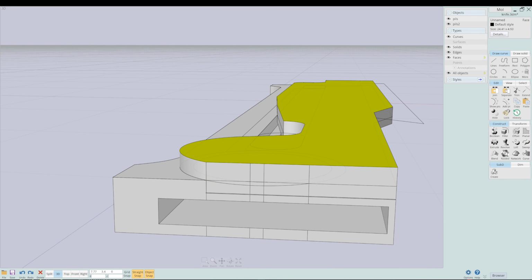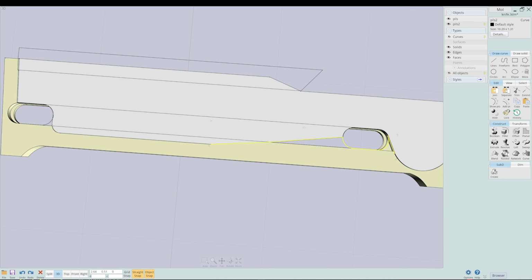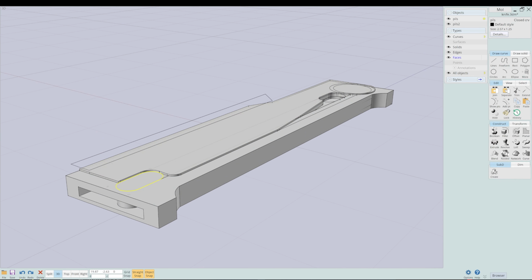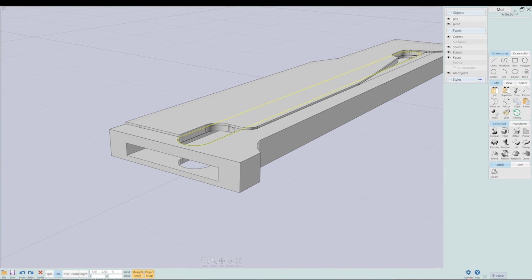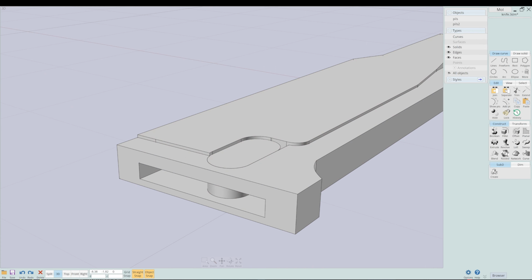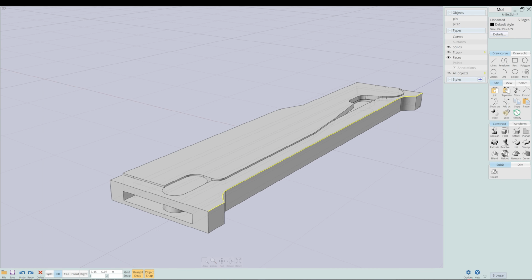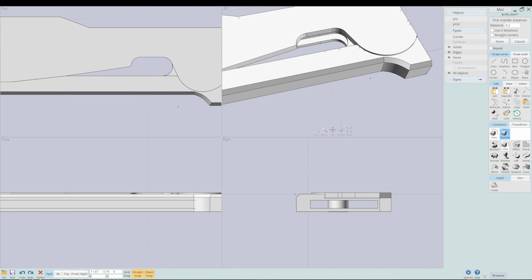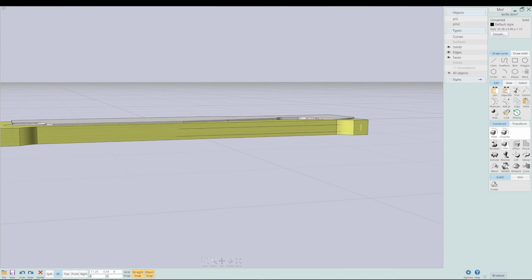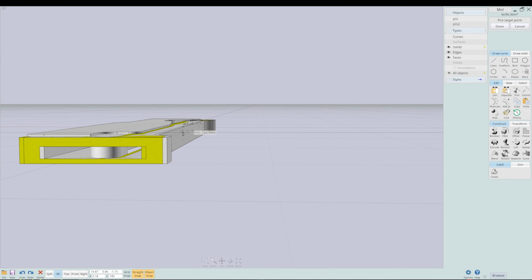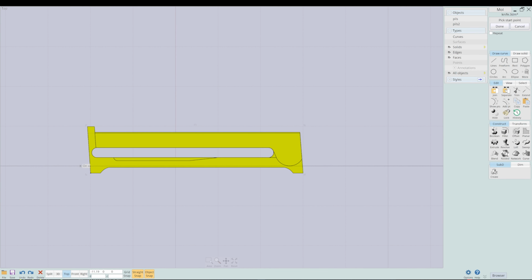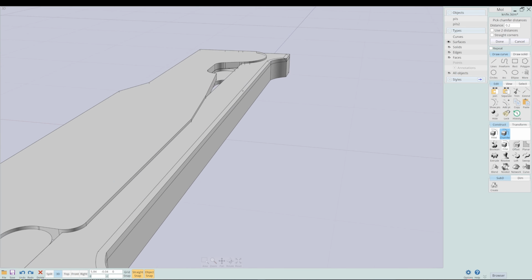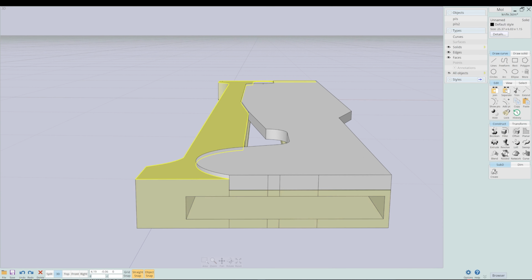The way that I set this whole build up in MOI here was slightly different than Plasticity. I think it probably was a bit more intuitive and a better way to do it in Plasticity, but in Plasticity I just cut the line for that top piece of the shape into the surface, and then used that surface to create the actual piece, and then continued building the piece.